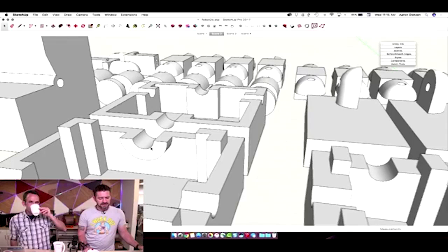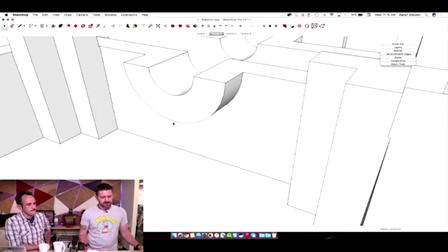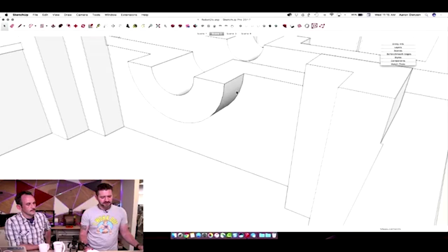Speaking of them, there is something else I want to point out right here. So I have these half circles that, like I said, nest these swivel pieces. Originally I had them modeled like this, just a simple half circle. And what ended up happening, of course, was because this piece is going to overhang in the printer, it has to print up support material to sit underneath here. It can't just print this out into space.